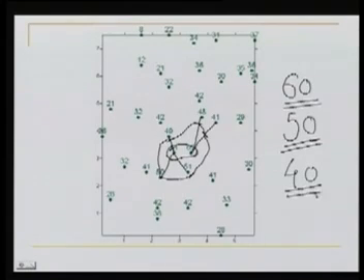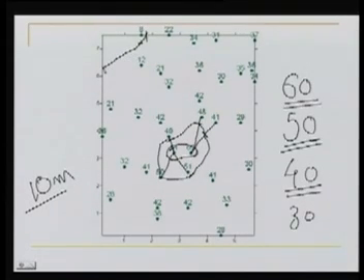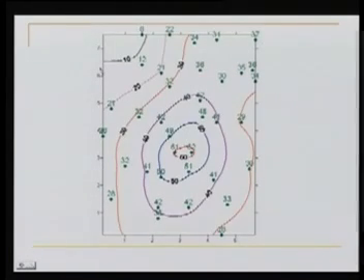Similarly, we can go for 40, we can go for 30 and so on. Now, over here, the contour of 10 meter. If we see the contour of 10 meter, between 8 and 22, if we consider it to be the uniform slope, the 10 meter contour should be here. 8 and 12, the 10 meter contour should be here. Okay, so we'll have a 10 meter contour which will go like this. So what we can do, we can plot all the contours for this area like this.